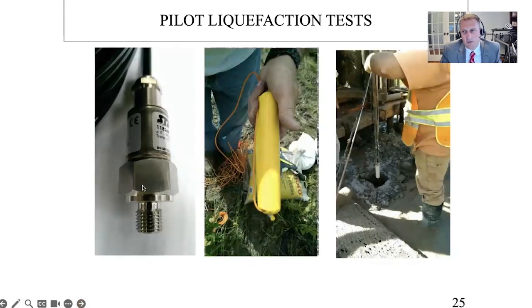So these are the piezometers that were used. These aren't vibrating wire. These are resistive gauges. We don't want to have damage from the blasting causing too much pressure on our vibrating wire gauges. And these are able to be measured more quickly. Instead of the repeat time on a typical vibrating wire gauge, we can record these in a quicker fashion. We use some emulsion explosives, and so that's what's shown here.